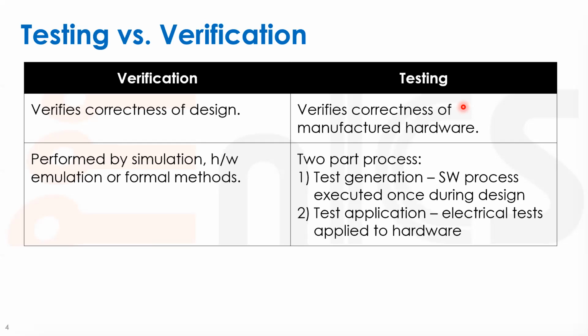Okay. The other thing is that the next step is that in verification, we do it using simulation. We can use hardware emulation, and we can use different formal verification methods. For testing, we do something very different that we're going to be discussing in this lecture. We're going to be doing test generation. That's something that we run some software that's going to make tests. Then we're going to take that software that we did independent of actual hardware, of having the actual hardware, and then we're going to apply it to the hardware using testers or different test setups.